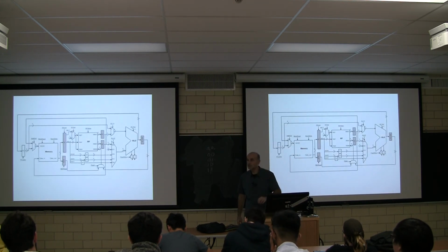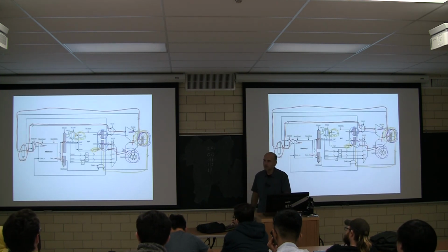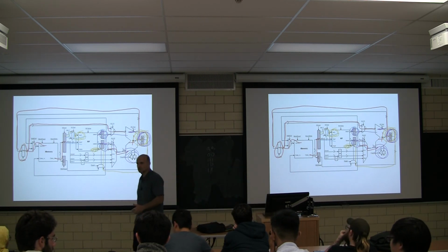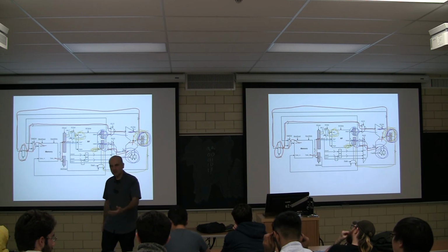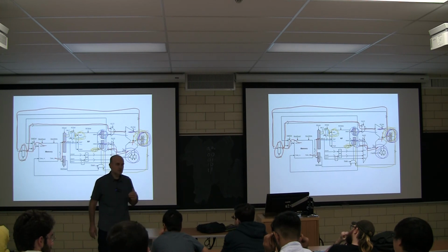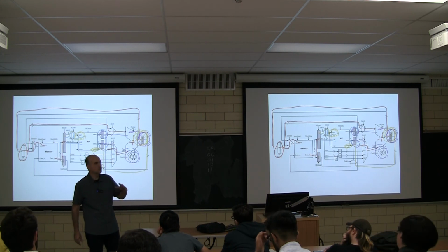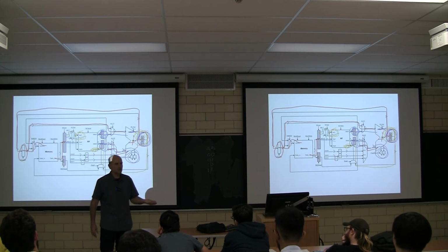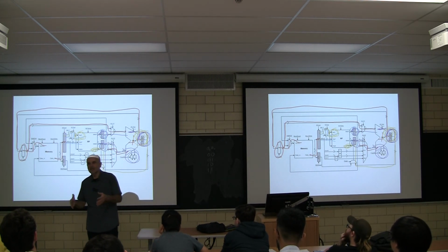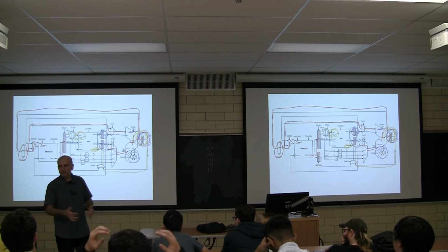Yes? What's the optimization in doing the PC plus 1 in the beginning? It's something we got to do because we had the foresight to design the instruction set so that all instructions do this and maybe some more. We can do it early on, cycle 1, rather than wait and make it happen at the end. If the branches did not have the PC plus 1 component, it wouldn't be possible to do this in the beginning with no cost. You can always subtract 1 and go back and fix it, but that will have more cost. But because we designed the instruction set so that part of the calculation of the next PC is always the subcomponent PC plus 1, we can do it early on in the beginning and never have to take it back.